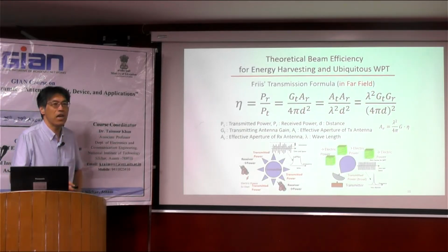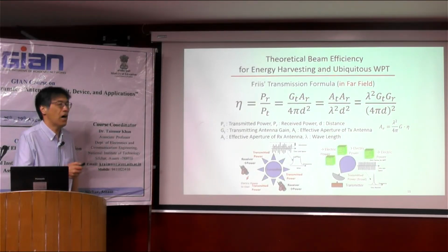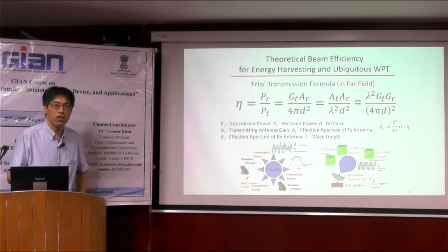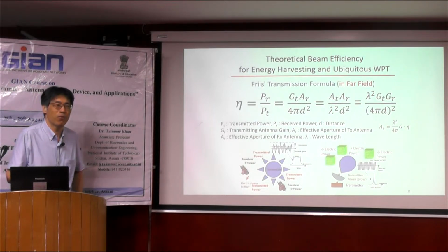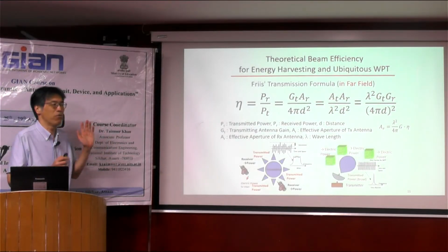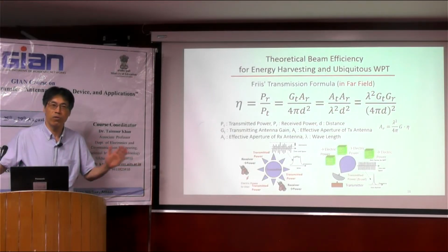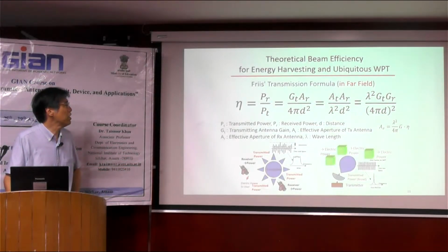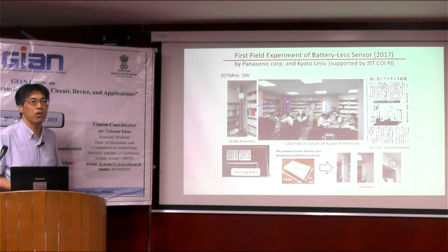as I mentioned again, in this Friis transmission formula, we assume the plane wave. This is the most important point today. So if you are in the laboratory of wireless communication, of course, it's easy to use this Friis transmission formula. There is no doubt. But please remember, it involves the assumption of the plane wave, long distance. So in this wide beam WPT application, the energy harvest application is an example in Japan, in Kyoto University.